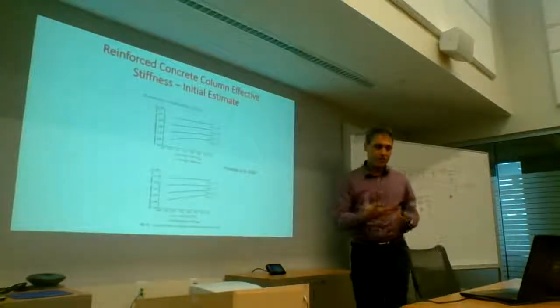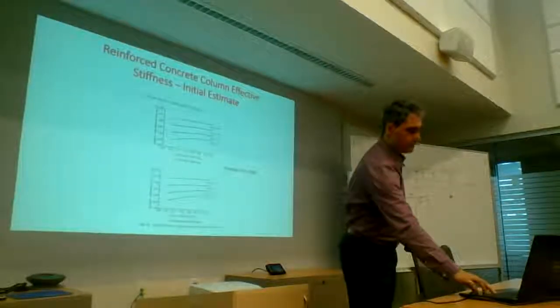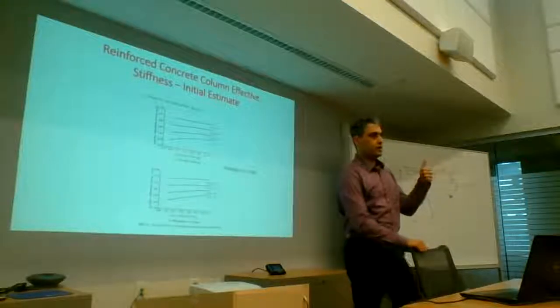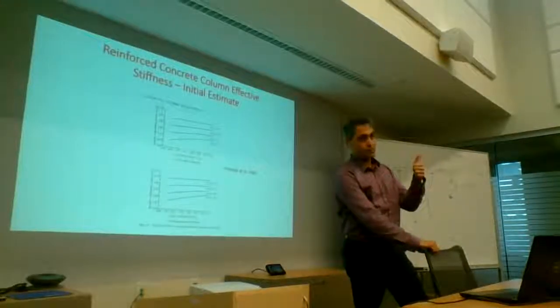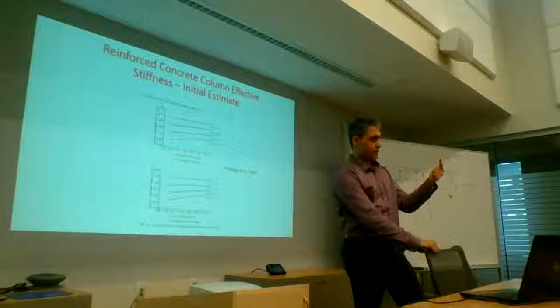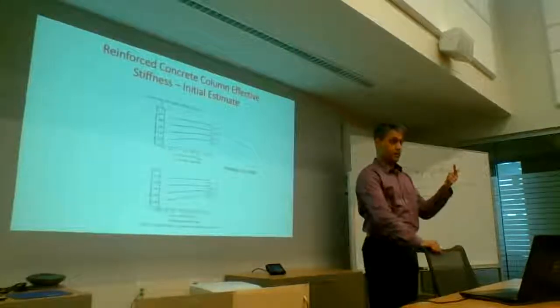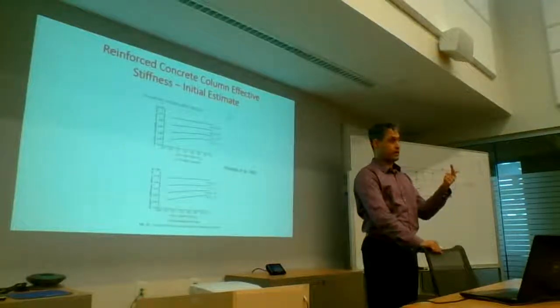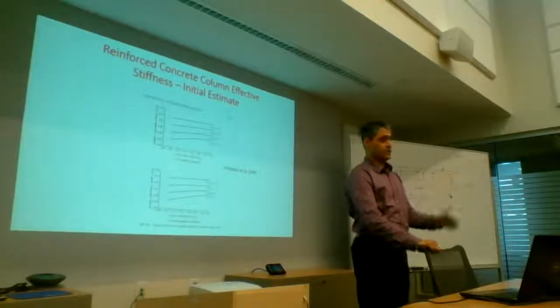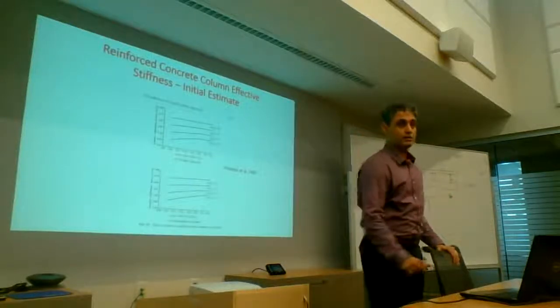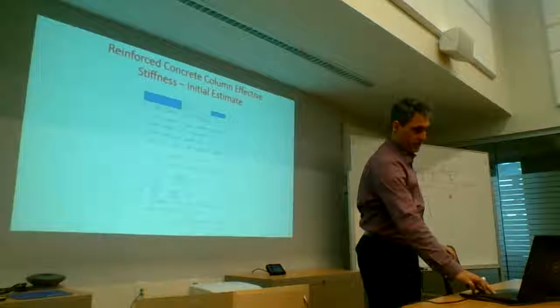And then try to stay within 1 to 2% rebar. Remember that the code bounds are 0.8% minimum and 4% maximum. But 4% rebar is really huge. And if you have to lap splice it, then you're looking at 8%. You physically can't get 8% rebar anywhere. You won't be able to do much with it.